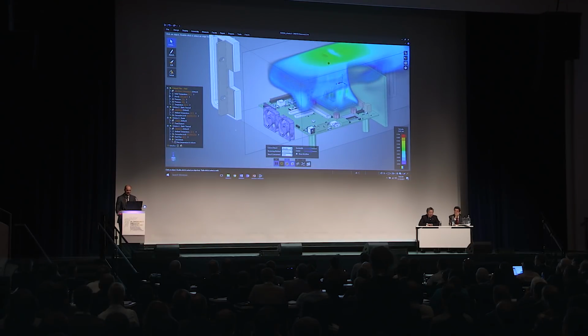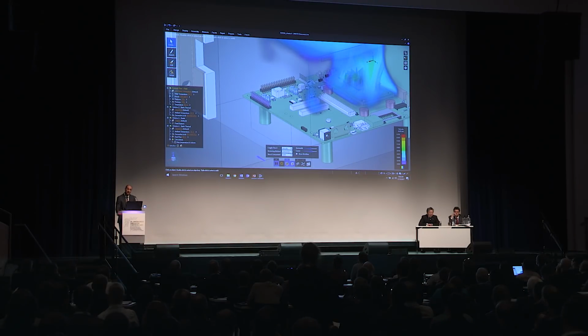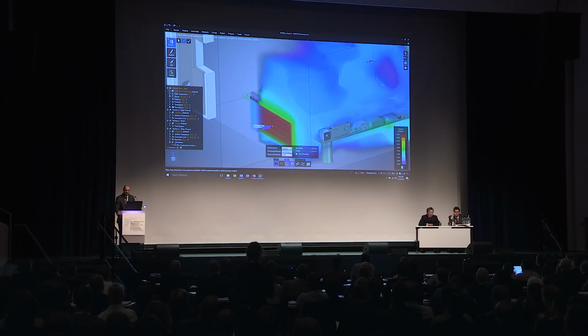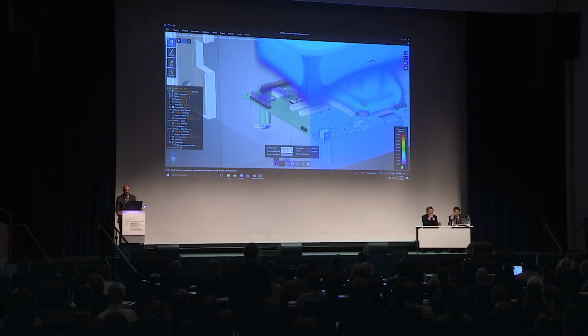Maybe, just because I can, let's turn the fans on inside this enclosure. All right? So we'll hide this one. And we'll come over here and select a few set of boundary conditions. We tried to keep boundary conditions really simple because this tool is tailored at designers, right? So we'll specify a velocity, maybe something like 4 meters per second. So suddenly we turned on this flow. And actually, we were looking at velocity the entire time. Let's look at temperature instead.